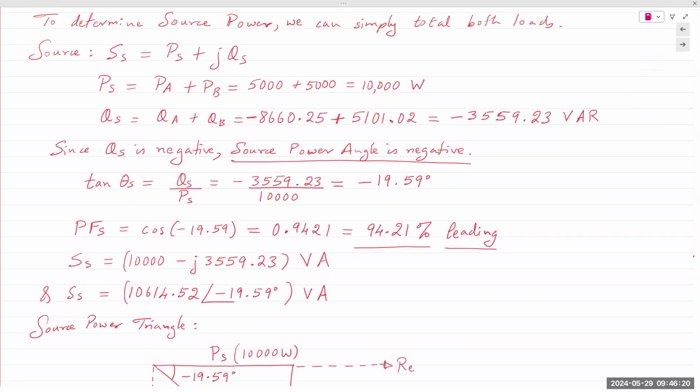So you have total Q supplied by the source as minus 3.5 kilo VAR, volt ampere reactive. Units are even more important in this case because the units will tell you the quantity. In the circuit diagram, nothing is given to you except VA and watts W. So it'll be your job to recognize it and then extract the information and understand what it is telling you.